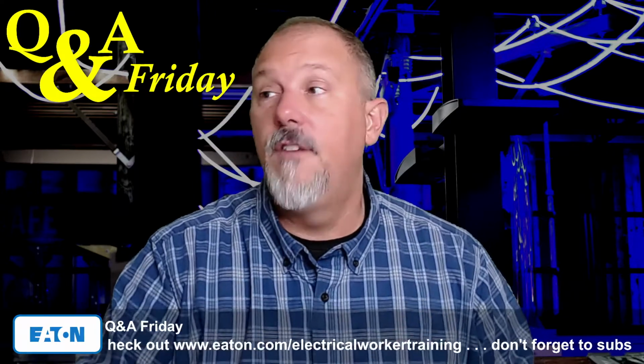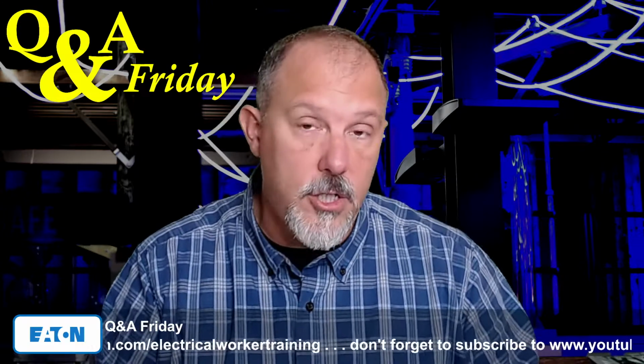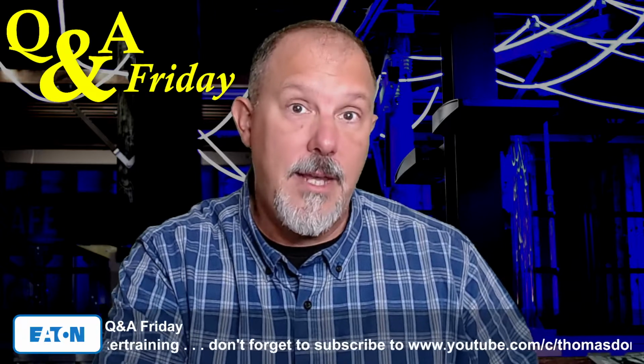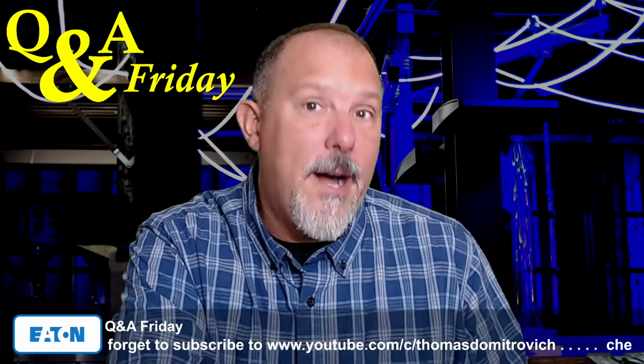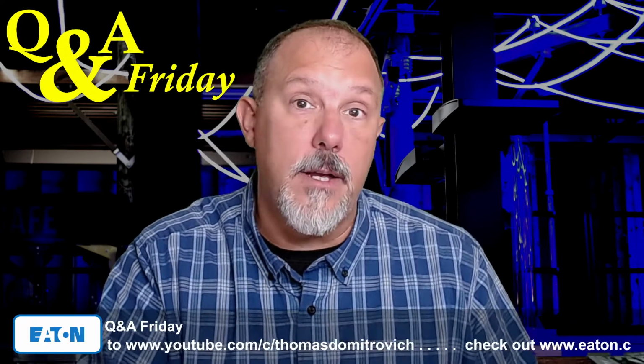Because I'll tell you, for example, medium voltage equipment is all 100% rated. There is no reason to do a 1.25 calculation on continuous loads. Yet, the sizing and whatnot still requires it, even for a medium voltage application, and that is not necessary because medium voltage equipment is 100% rated.